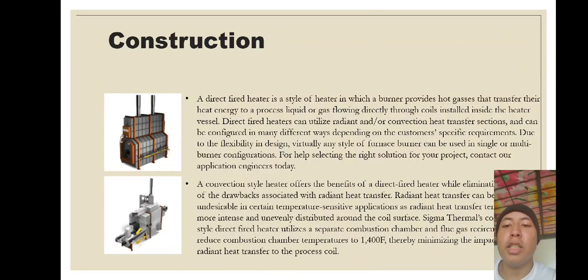So, for the construction, a direct fired heater is a style of heater in which a burner provides hot gases that transfer their heat energy to a process liquid or gas flowing directly through coils installed inside the heater vessel. Direct fired heaters can utilize radiant and/or convection heat transfer sections and can be configured in many different ways depending on the customer's specific requirements. Due to the flexibility in design, virtually any style of furnace burner can be used in a single or multi-burner configuration. For help selecting the right solution for your project, contact our application engineers today.